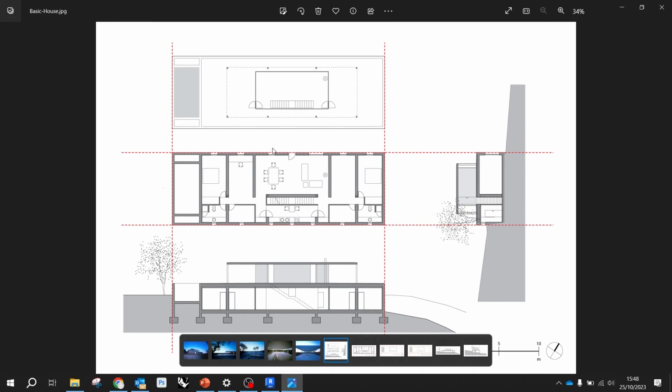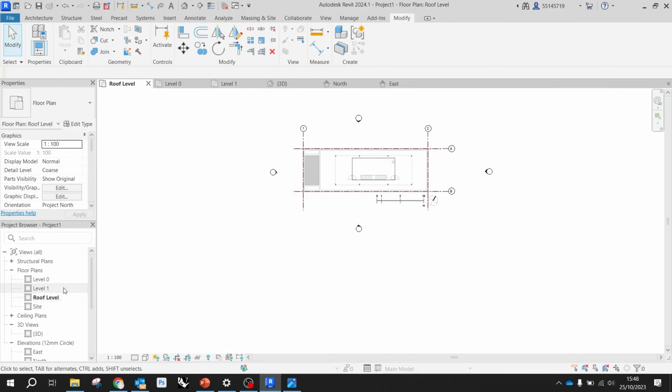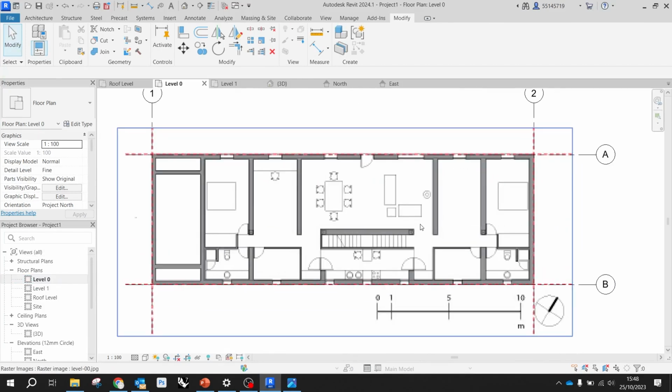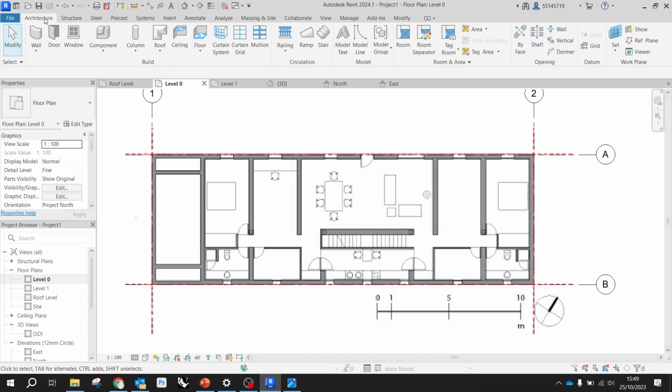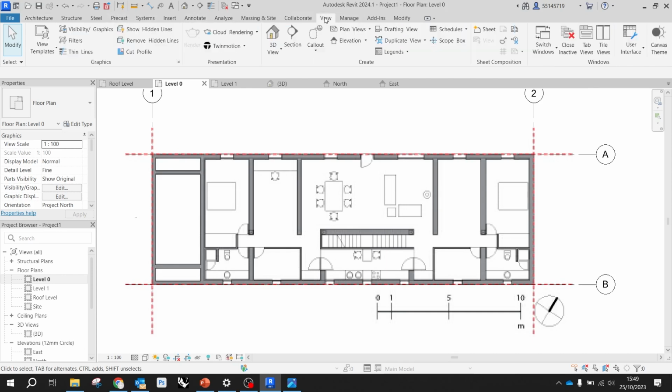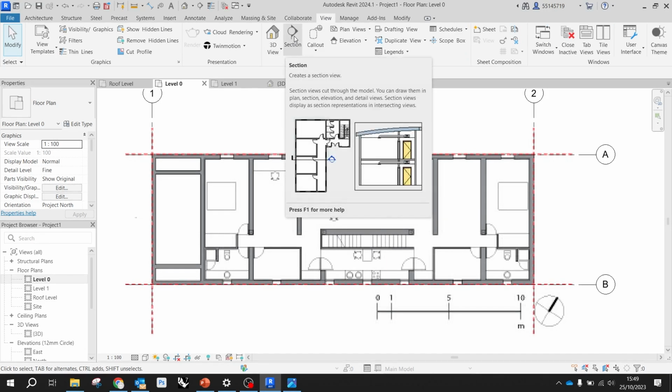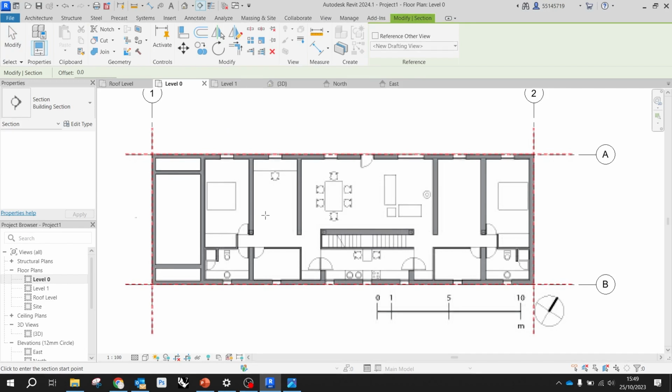So in Revit, you can create sections, right? So I'm gonna close this. I'm gonna go to level 0 because it's gonna be easier for us to find where the sections are looking, at level 0, where we have the interiors, according to what we just said. And there is a specific tool to create a section, which is called section, exactly. Don't need to be too creative, just section. You find it under View, right here next to 3D view, you have section with this arrow, right? So if I click on it, now I can draw my section.